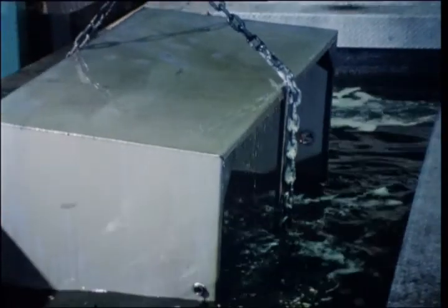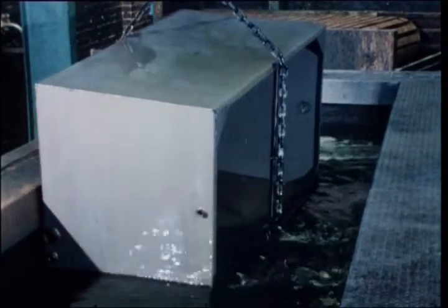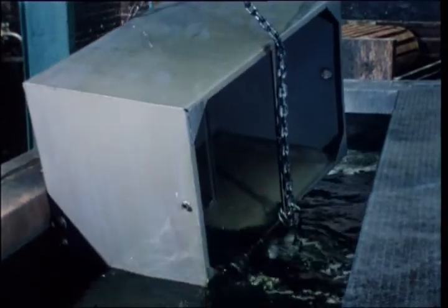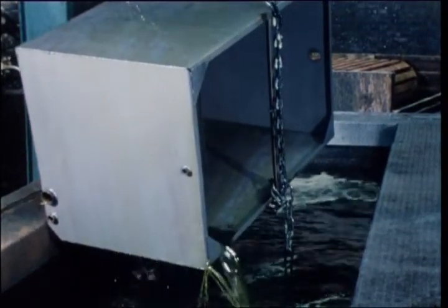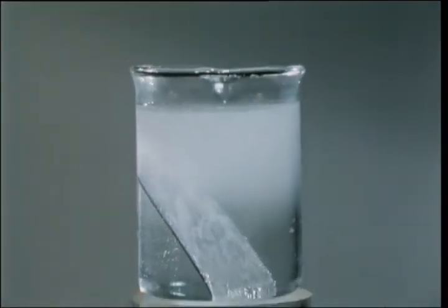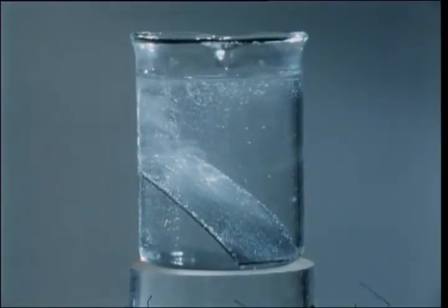Steel is commonly cleaned in acid to remove scale and rust. But an inhibitor is added to stop the acid attacking the metal. When pickling acids attack steel, hydrogen is evolved. But even a minute amount of inhibitor will slow down corrosion and therefore the production of gas.